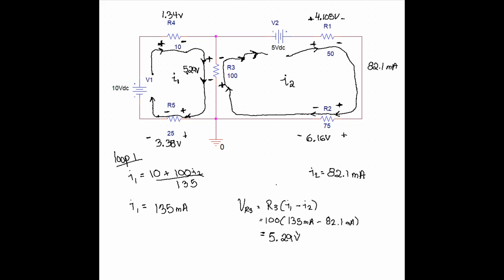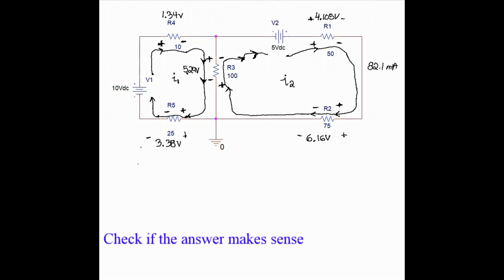Now, it's always a good idea to determine whether your answers make sense. Do the answers make sense? Is there a quick way to check? Yes, we can check simply by applying Kirchhoff's voltage law. Do the voltage drops in each loop add up to 0?